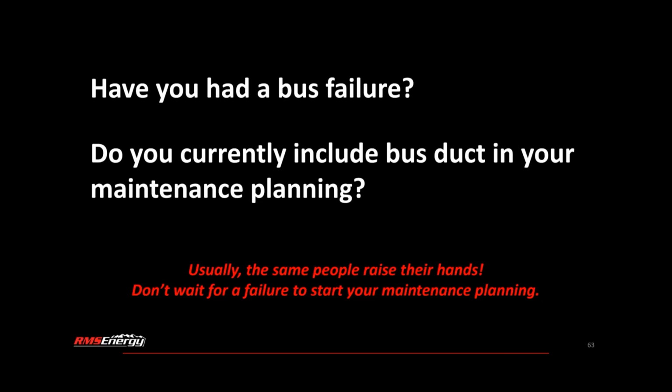Really the reason that the interior is painted is for heat dissipation, to support radiative heat transfer. So you may lose some cooling capacity, but if you're monitoring your bus and there are no hot spots, I don't know that I would go through that much effort to repaint the inside of it. More just monitor the critical components we talked about today. Make sure you aren't experiencing any heating issues or major corrosion issues after you repair the significant damage there.